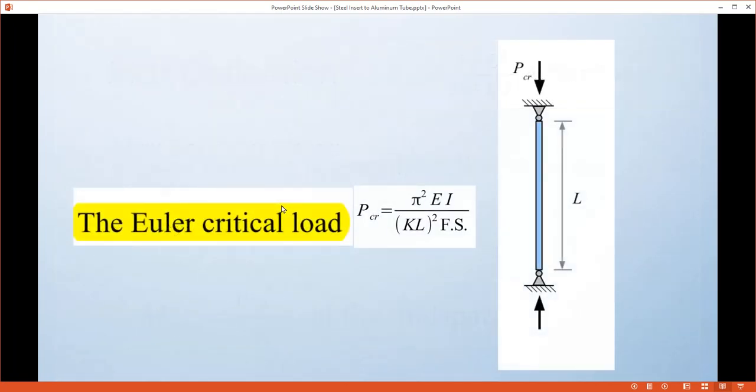So you also increase the vertical load capacity based on the Euler equation, since the load is proportional to the moment of inertia and the Young's modulus. E is Young's modulus and I is moment of inertia. So as moment of inertia gets bigger, your vertical curtain wall gets stronger to hold the dead load.